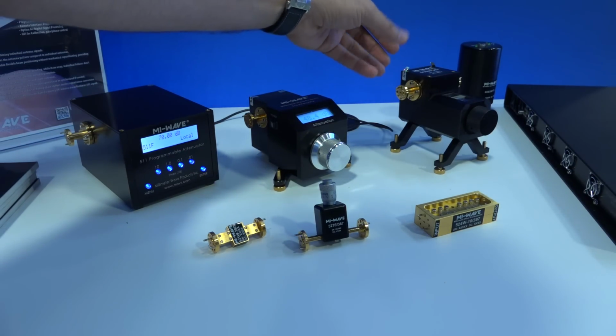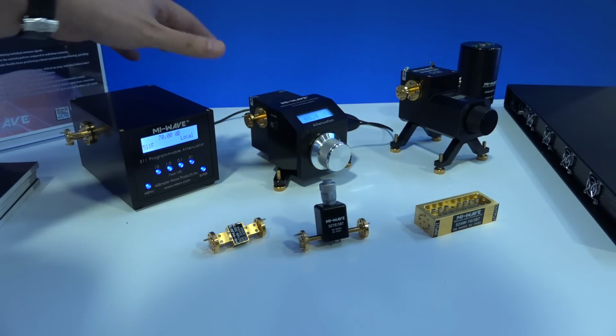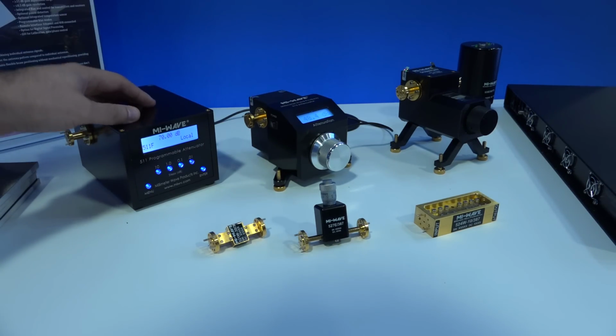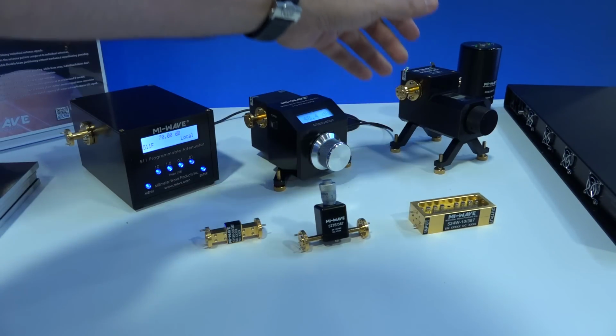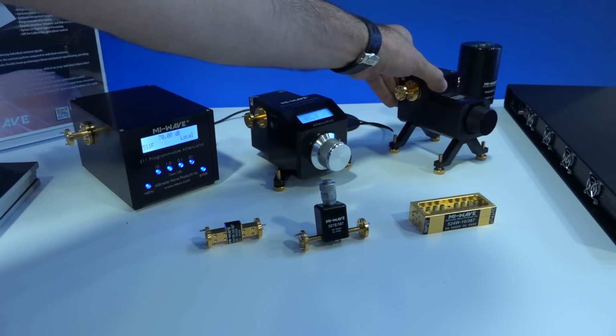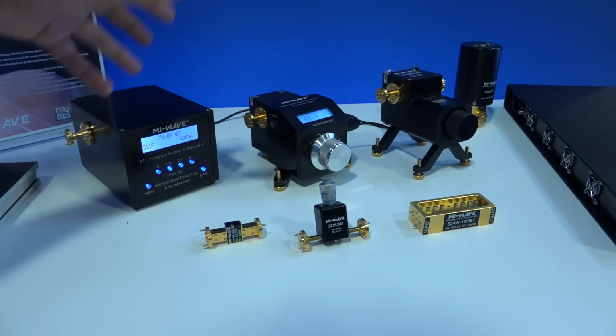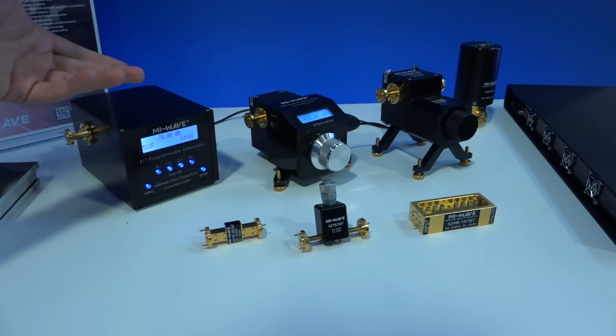And this is of course the old version of it where everything is manual, but this is super helpful if you want to do a repeated measurement and you want to go between large dynamic range of attenuation. We do have fixed attenuators, we have high power attenuators, and we do have electromechanical switches to switch various waveguide ports. So these combinations are quite useful in the lab, especially if you want to move things around.